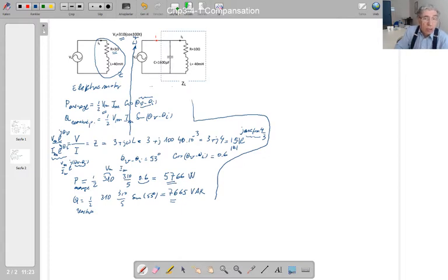I am saying the current that we consume here is not going to change whether you are in this circuit and this circuit. Why is that? Because this power divided by this impedance gives you that current, isn't it? It is also true for this one, because we already said that this power is the same as this element power. So if I divide that voltage by this equivalent circuit impedance value, I'm going to get the same current here and the same current here. So if the voltage and current of this motor is not changing whether you are in this circuit and this circuit, that means you're going to get the same average power.